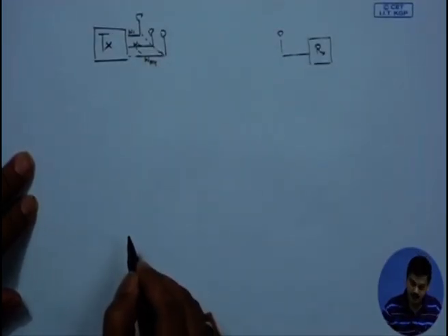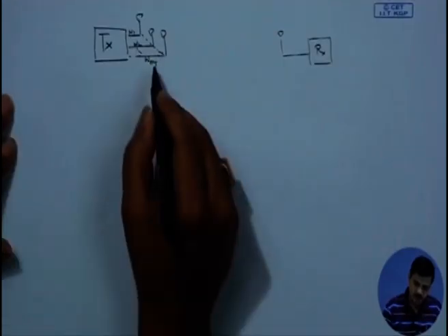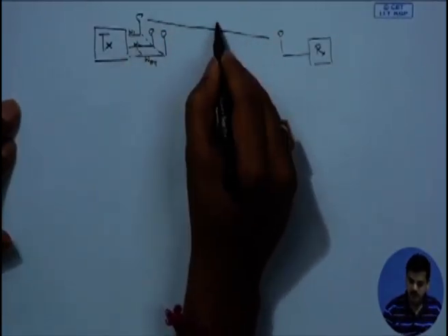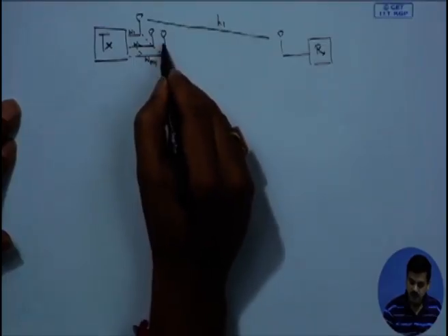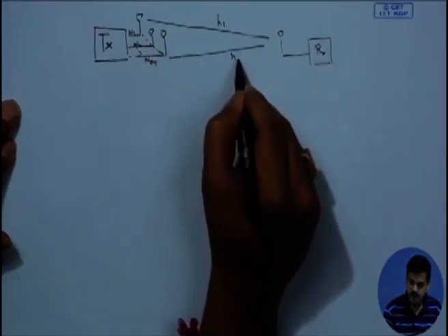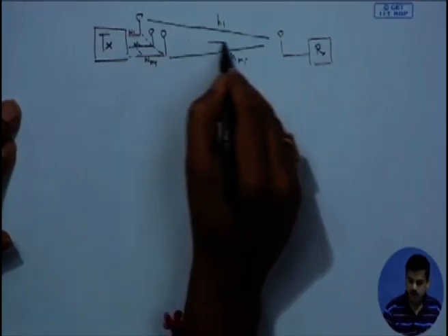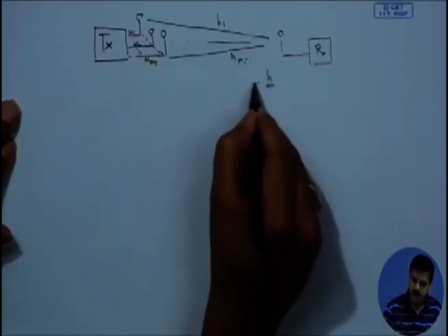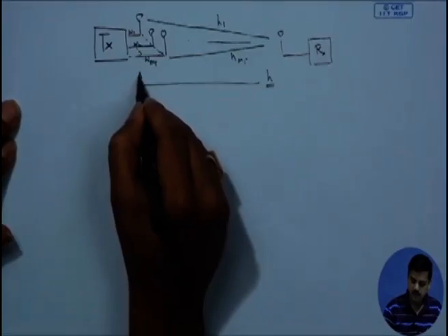That means we had weight factors and these weight factors were proportional to the channel gains. So if this particular link was H1 and the last one was H_MT, we had all these links. So this entire channel vector H had to be fed back to the transmitter.